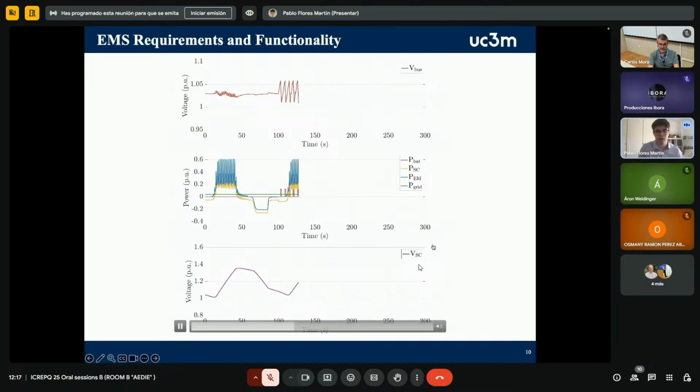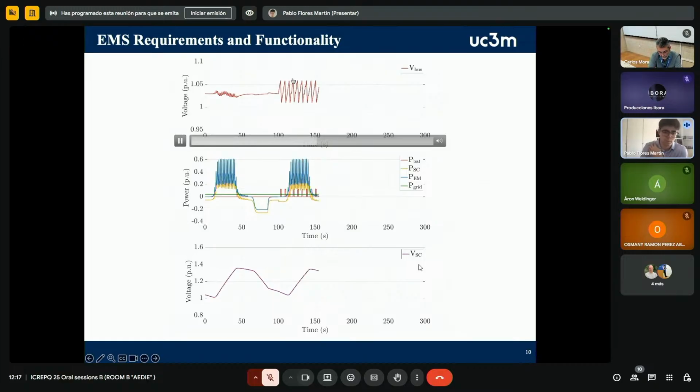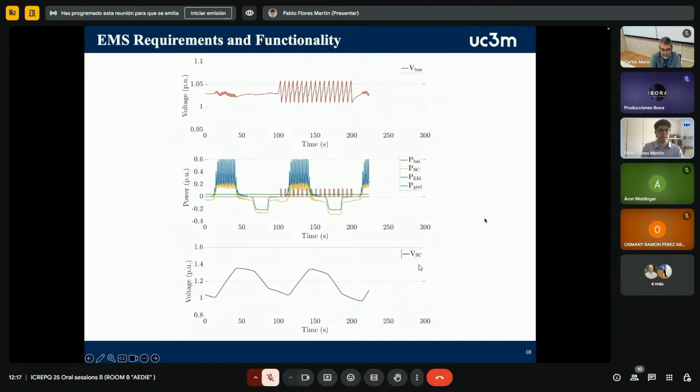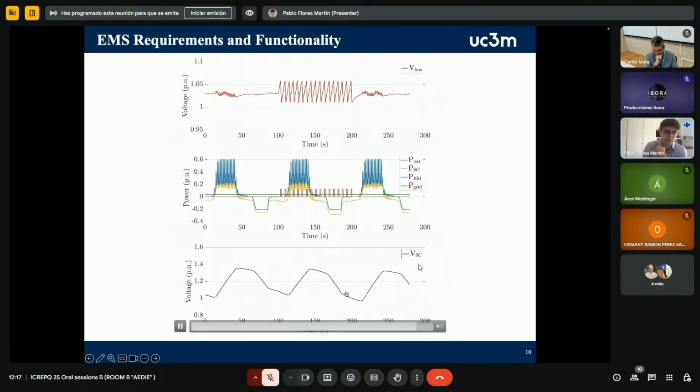be seen here. This causes a gradual rise of the DC boost voltage, and once the boost voltage exceeds the battery activation threshold, the battery begins to absorb power to bring the voltage back down. This process repeats until the end of the cycle, where the supercapacitor, because of the offset, reaches its reference voltage. Therefore, during the third cycle, no battery intervention is needed.